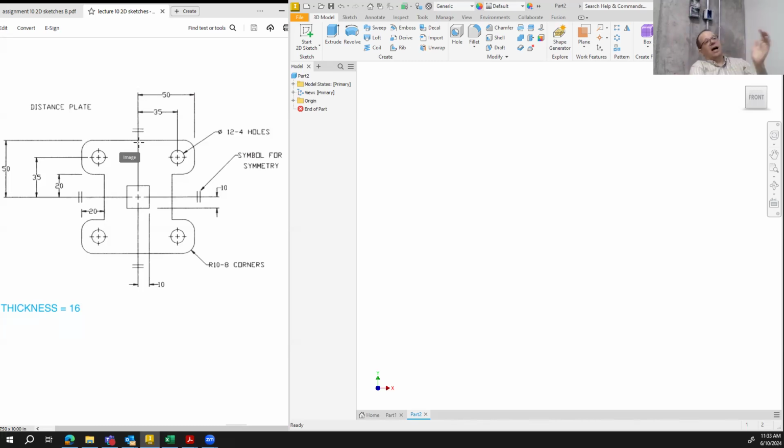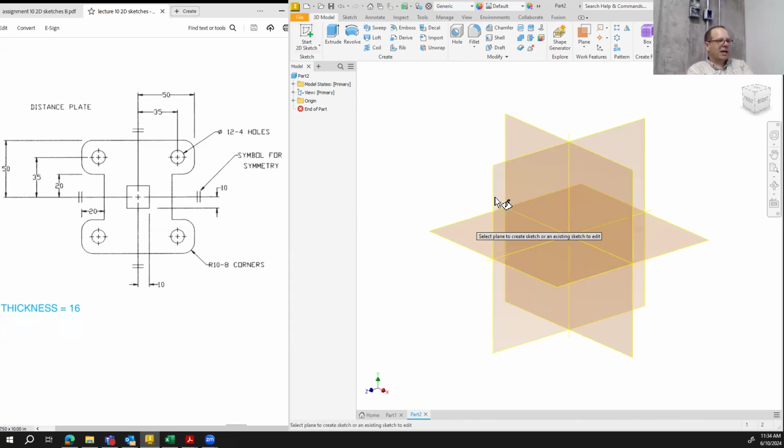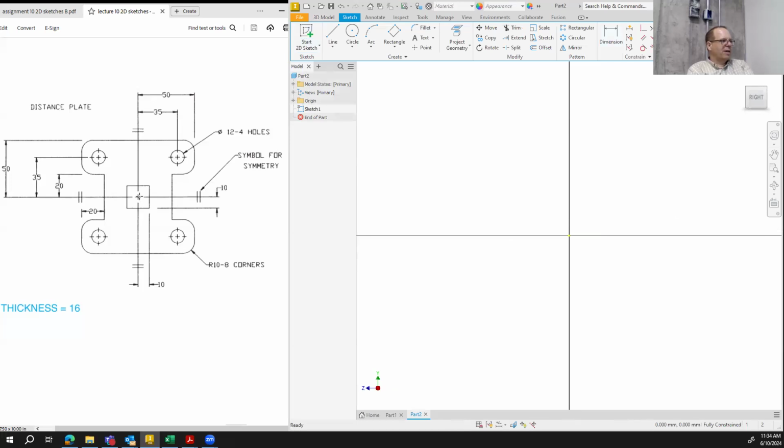In this case, I'm not exactly sure it's the fastest way of doing it. I think the fastest would probably be to draw one big rectangle, do another rectangle, trim the holes, and you're done. But in this case, let's practice the mirror command. So I'll do a sketch. Again, we're going to start here and draw a rectangle. We're going to start here, go there, and back.